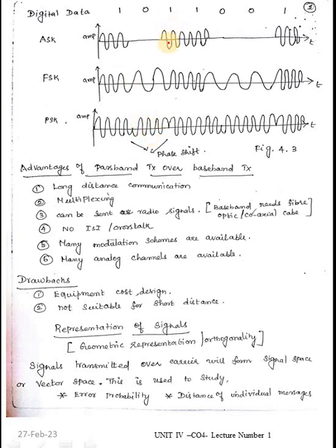Wherever we find the levels, binary bit 1 and 0, there we can identify the phase shift. Here the input data is 1 1, so there is no change in phase and the same data is transmitted. Here we have 0, so there is a phase shift. So here bit reversal is obtained. This is the general representation of shift keying.